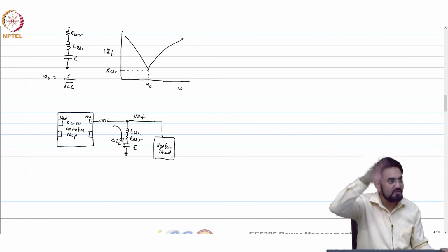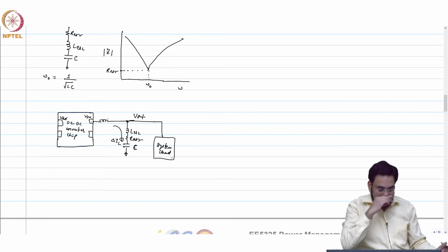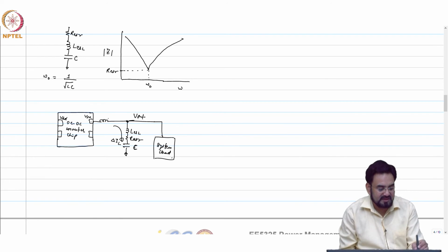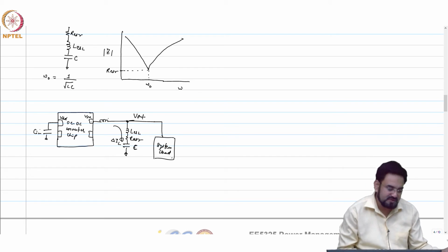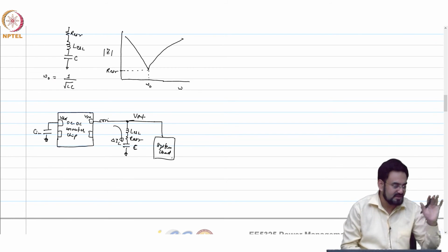It will go from 0 all the way to load plus your ripple if you look at the peak. So in that case you cannot even afford to have a longer trace when you are connecting the capacitor. And this we call the input cap. So you have to put this decoupling cap at the input always. Without this it will not work.